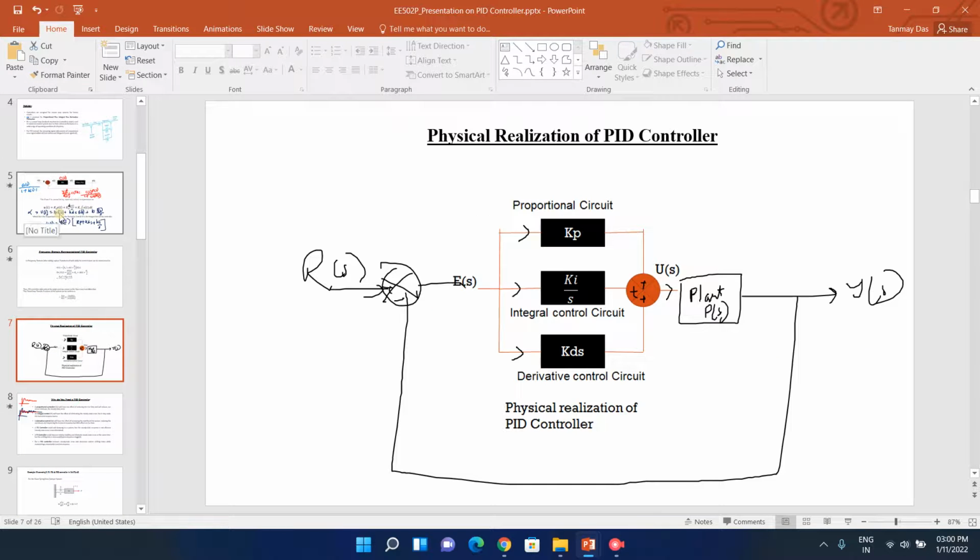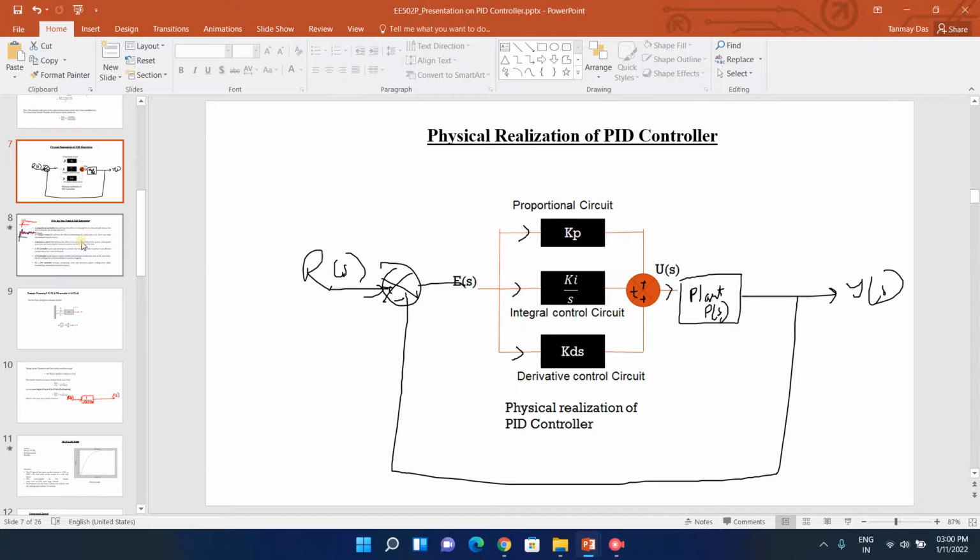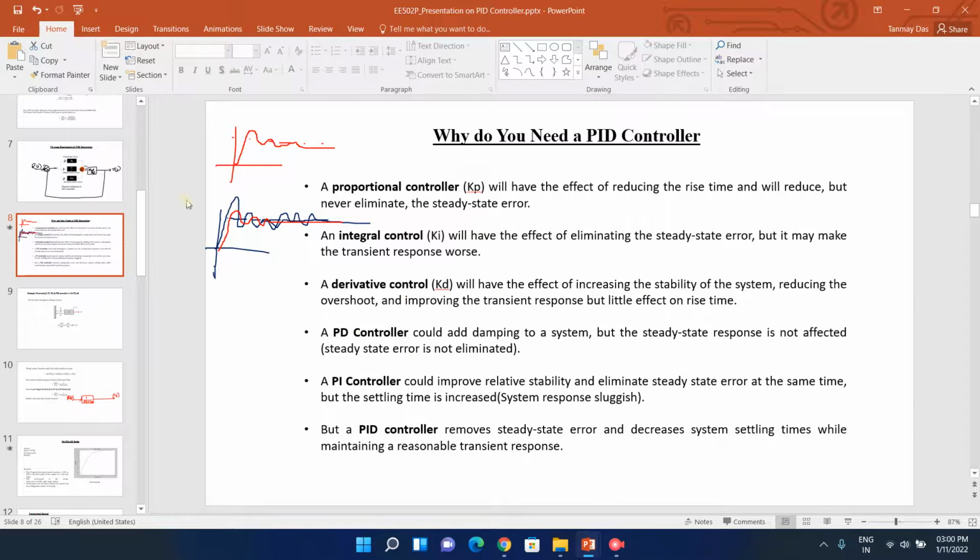Okay, before Matlab opens, tell me, have you understood this particular portion of the PID controller? What are the differences between PI, PD and PID? This one is very important. Derivative controller will help you act upon the rate of change of the error, so it will minimize the overshoot. It will stabilize faster and increase the stability.